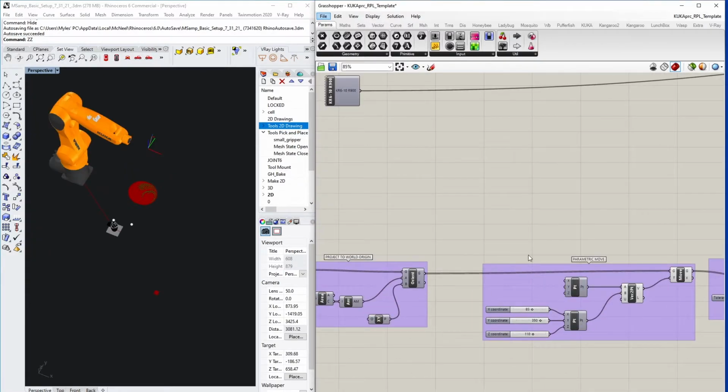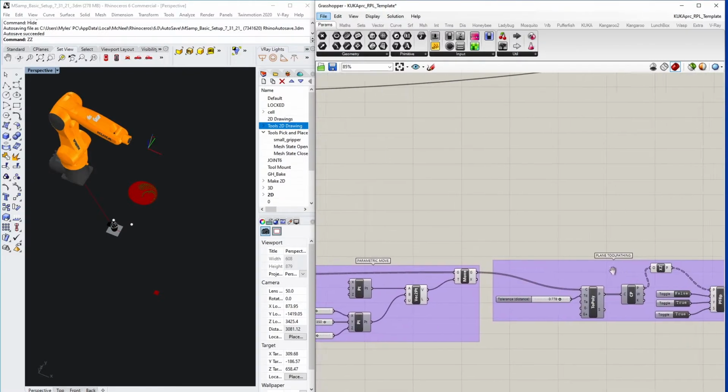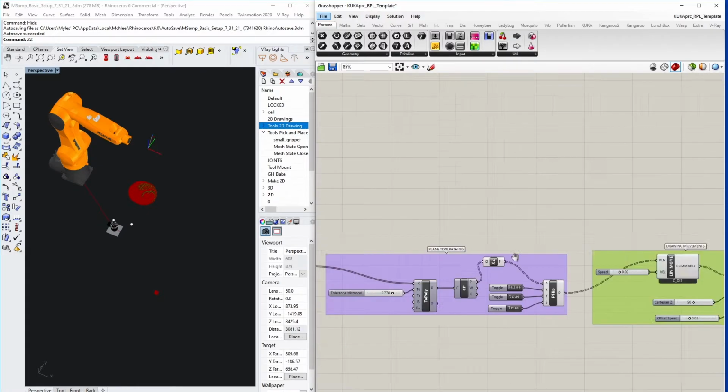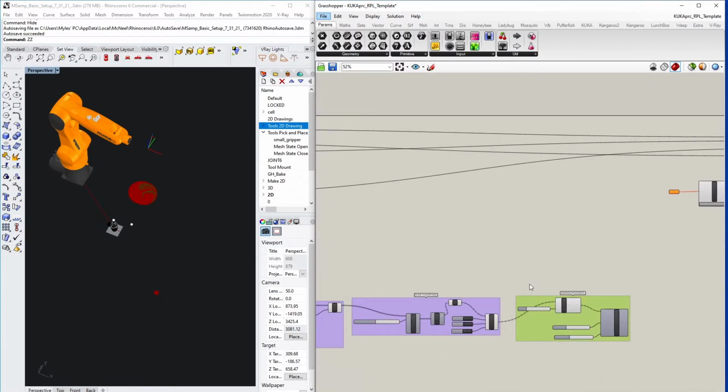What we need to do is actually pull out the first plane over here in this list of planes, and then give it a copy and move that copy in a way that it's positioned right above our first point. So there are no extra rotations along any of the robot's joints.